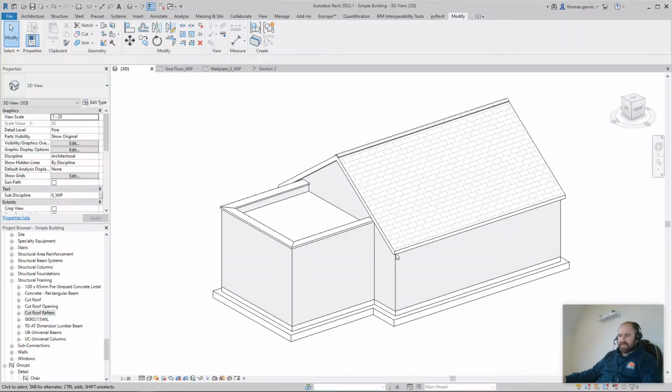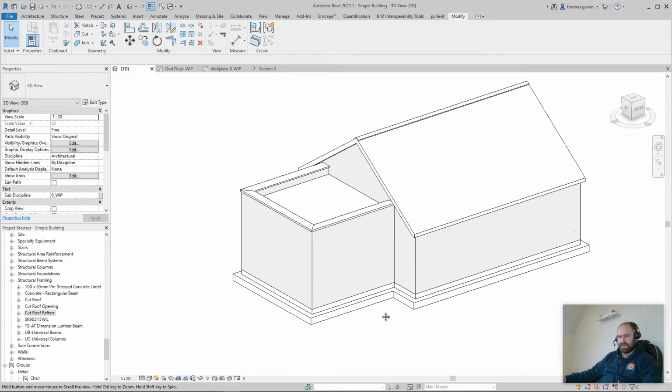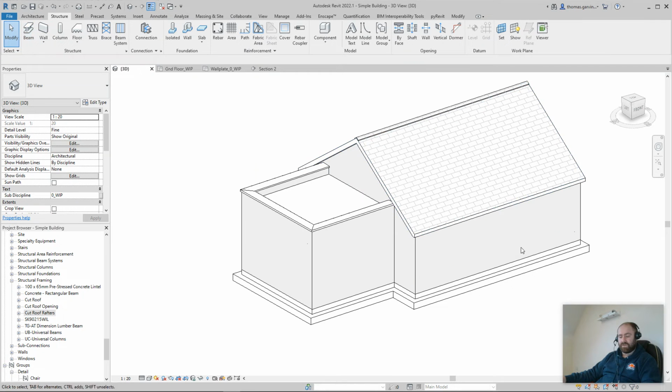Hi, how you doing? Today we're going to make a furring piece family to put into our flat roof, and we're going to also modify our flat roof to take the shape with the gradient and so on. And we're going to take a quick look at the flat roof first, and then we'll go on to making a furring piece family. Okay, we're going to make the family, by the way, out of a generic model line-based template, and then we're going to recategorize it as structural framing so that we can place it from the structure tab and beam. Okay, escape.